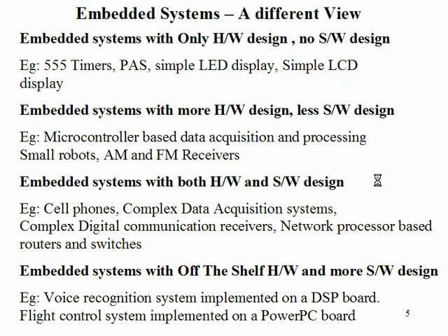If you take some types of embedded systems which may be purely hardware, there is no software involved in it, almost like some alarms based upon 555, it is only hardware level of design. You design appropriately the resistors and capacitors to achieve your duty cycles or whatever the time or delays, that's all. So there is no software involved in it. Generally they are very simple embedded systems.